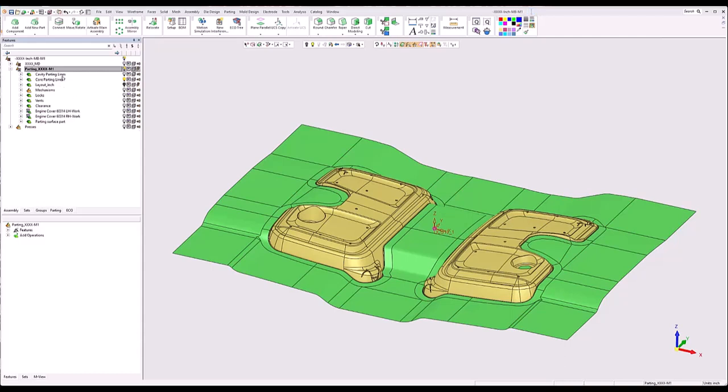Inserts could be in core and cavity sides, but you can do all these features or modeling inside these skins and then use the skins to cut the core and the cavity block. If you put those modeling features into the core and cavity block, what it does is causes regeneration to take longer, particularly if you're doing stitches and you have multiple stitches in a core and cavity block. It really becomes noticeable when you edit, move a screw, remove a screw. It takes longer to regenerate through those.